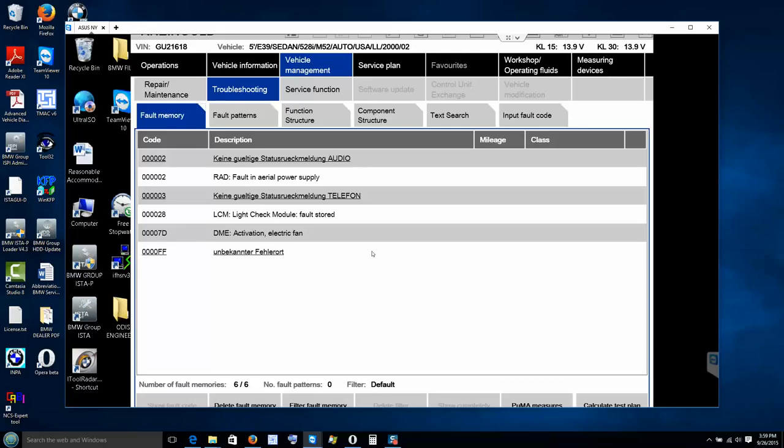Okay. Well, the FRM needs to be reset. It's a fault counter. The fault counter will reach a maximum, I don't know if it's 50 on the E39. Each time you turn the key on, it still detects the fault and increments the count by 1. So BMW allows it to max out at 50. You can reset it using Toolset 32, or we can use ISTA/D to reset it. We can try here if you want. Yeah, let's try that.